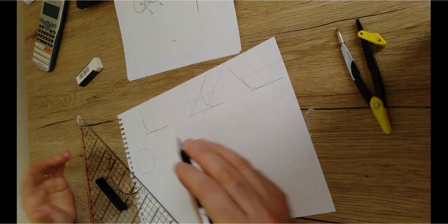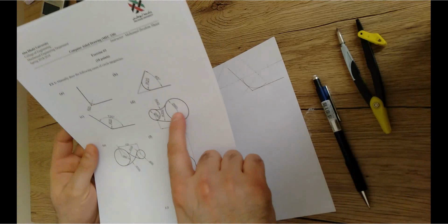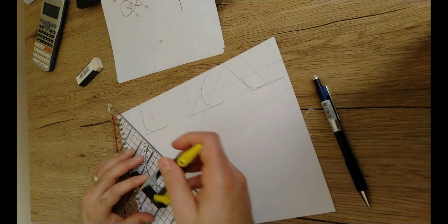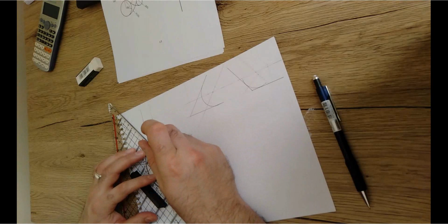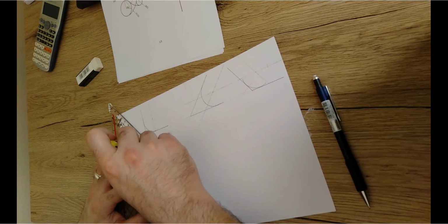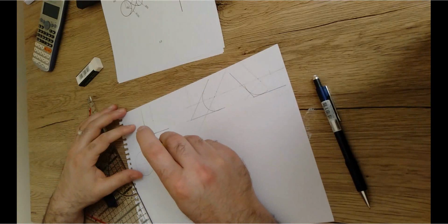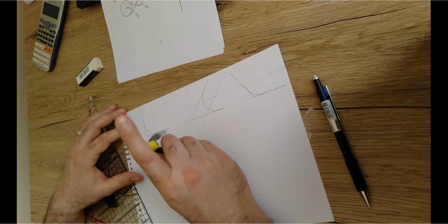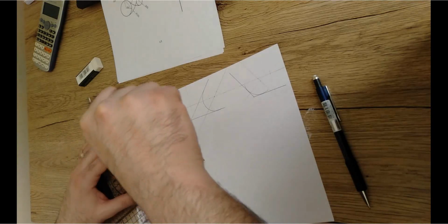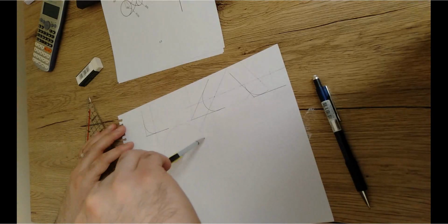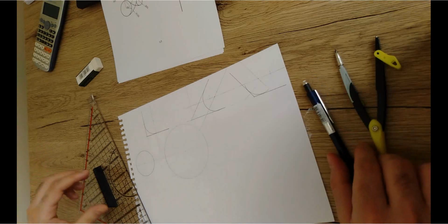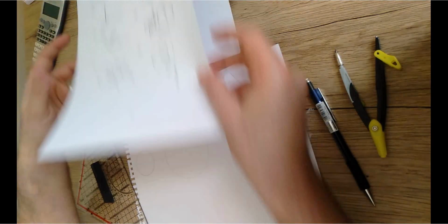This point is gonna give us the center of the second circle, and the diameter of the second circle is already given by 80. It means that the radius should be 40. So I'm gonna open the canvas twice, or double the diameter, so it should be like 40 millimeters opened. And from this center point, I'm just gonna draw the second circle. So this is gonna give us like another big circle as given here. Make sense?